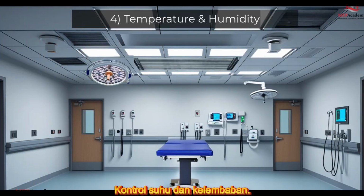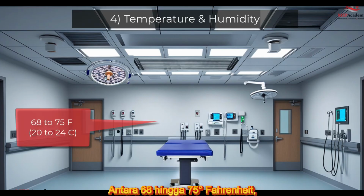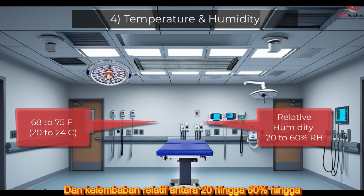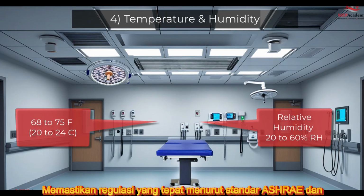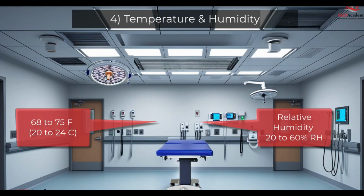Takeaway 4. Temperature and humidity control. Operating rooms must maintain temperatures between 68 to 75 degrees Fahrenheit, 20 to 24 degrees Celsius, and relative humidity between 20 to 60% to ensure patient safety, staff comfort, and infection control. Tight control prevents microbial growth, high humidity, or static electricity, low humidity, with building management systems, BMS, ensuring precise regulation per ASHRAE and FGI standards. System temperatures can be set lower depending on the specific requirements of the operating room or staff.